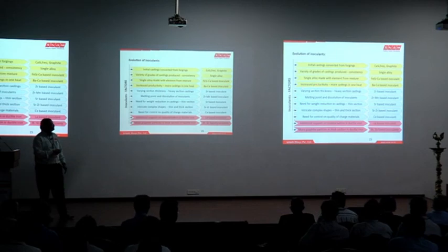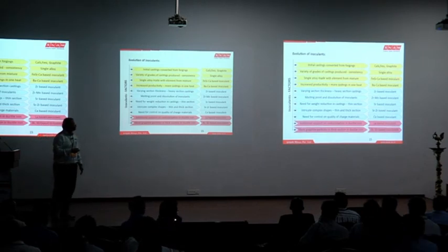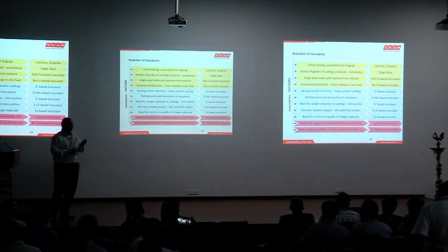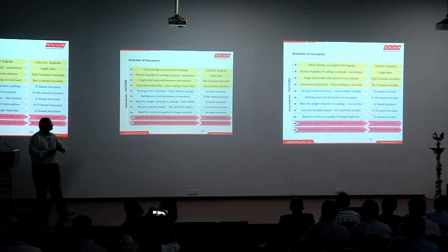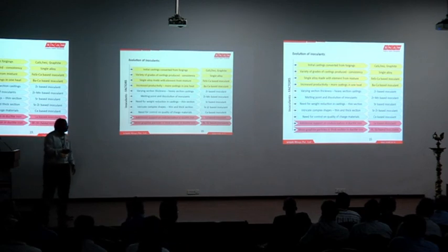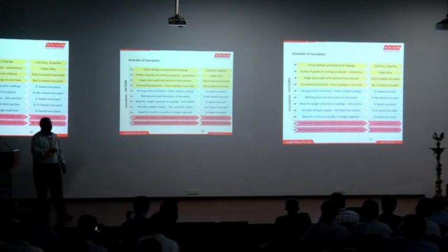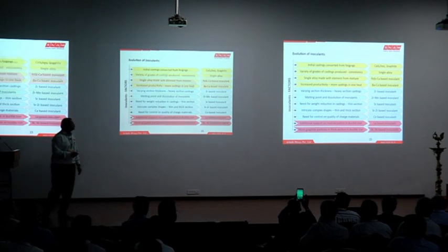And when productivity increases, in this scenario, if the castings were performing well and they wanted more castings, and a productivity requirement came up, say you wanted to pour more boxes, more castings, so a long pouring time, the sustainability of the property of the liquid metal and casting throughout the time, barium or calcium inoculant would have come up. And when varying section thickness come up in heavy sections or thin section castings, zirconium inoculant. So these are some of the requirements and evolutions of casting industries and how these inoculating elements would have appeared in relationship with the evolution of the casting industry.